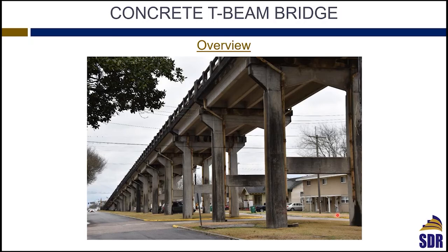In general, reinforced concrete structures have a lot of redundancy inherent in them. They are not the same as steel structures, and maybe they are not even the same as precast concrete structures. In reinforced concrete structures, when we have a beam and a column, we assume the beam is simply supported and resting on a column. We assume this beam will have a hinge and a roller, and when we solve this beam, we develop a positive moment of WL squared over 8, as simple as that.